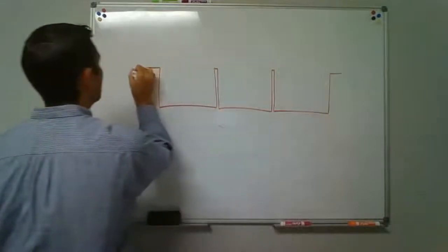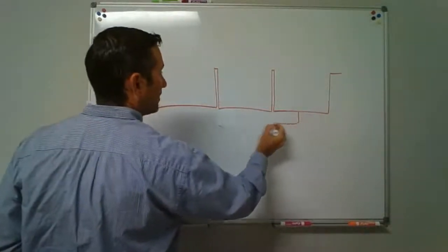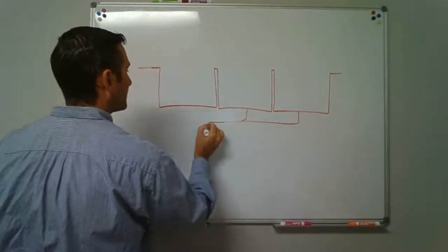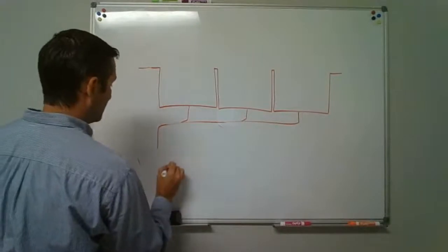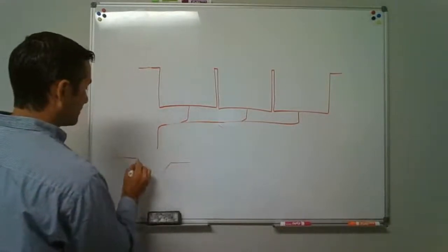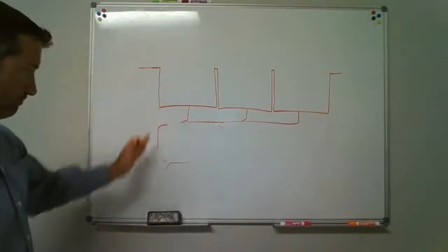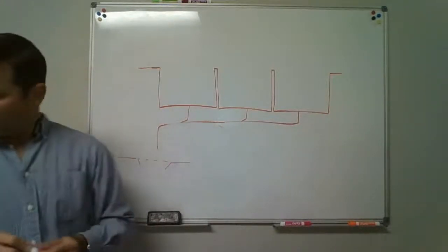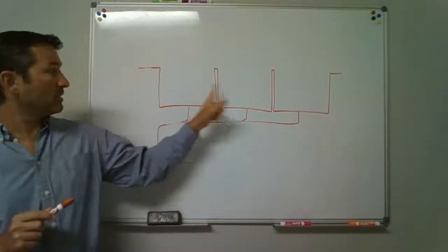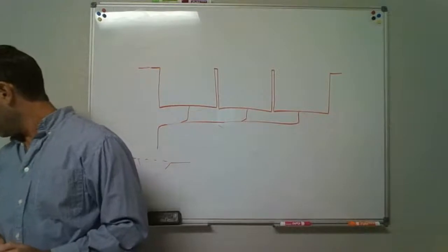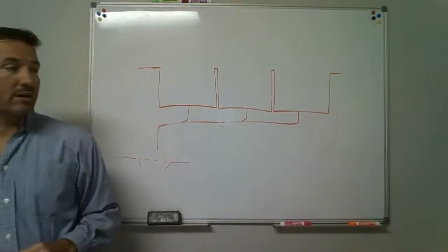All right. Now, what you used to see is one might come down, come across, pick this one up, come down, pick this one up, and then discharge over into some type of floor sink or something there, okay? The grate on that. And it would discharge in. This one is telling you that each well of a multi-compartment sink, we got 3 of them there, shall discharge independently to a waste receptor.